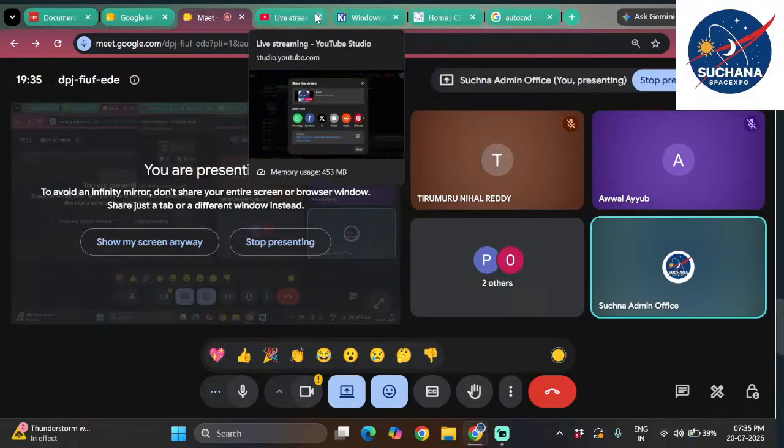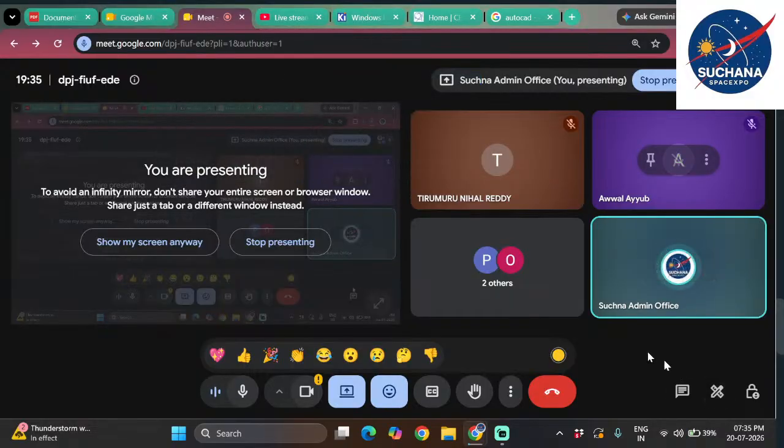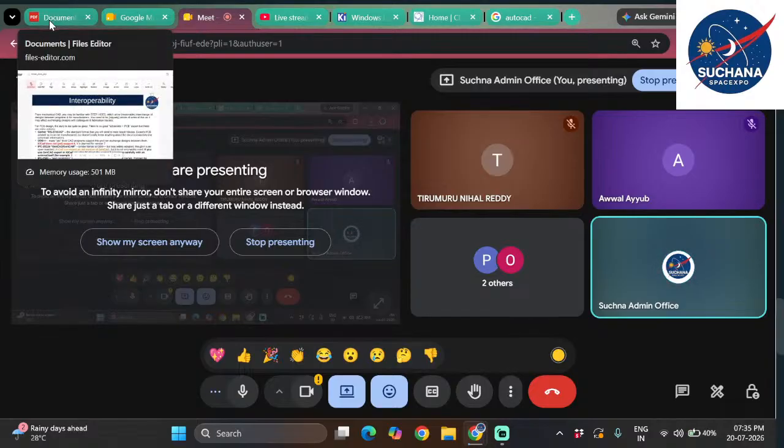Okay, so why do we need to learn about dot step and all these things? We haven't discussed these details in EasyEDA. But why is it very essential to learn in KiCad? Okay, I'll show you. This is actually the drawback of EasyEDA. It's not very easy in EasyEDA to import external 3D models and assign them to a particular component, but it is extremely easy in KiCad. You can import the external 3D models into PCB design, and there are lots of interesting things than in EasyEDA. Okay, we will reveal them one by one during the course.